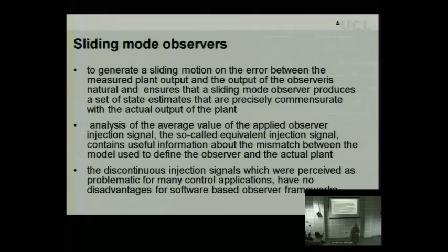And if you want to zero something, no matter what it is, whether it's to drive a state to the origin, whether it's a tracking problem and you want to zero an error between a desired position and an actual position, or whether you want to design an observer and make the error between the output of the plant and the output of the observer zero, you can't get better than trying to apply a sliding mode technique, because a sliding mode technique will give you zero error in finite time.